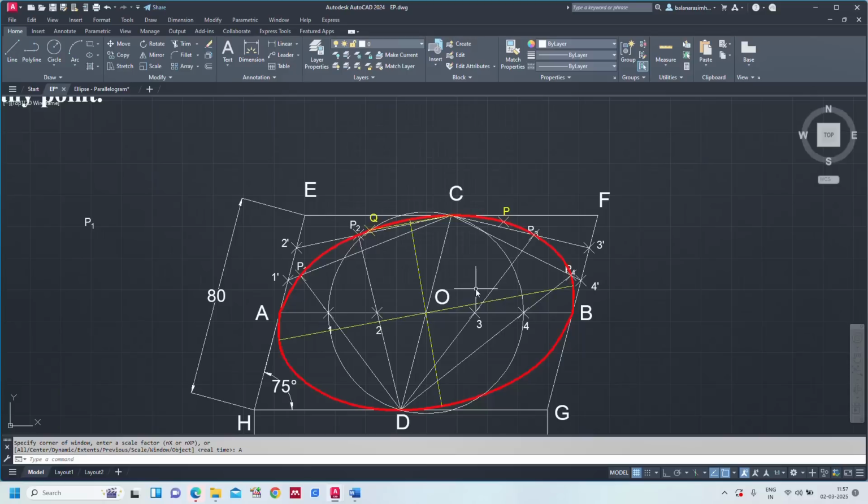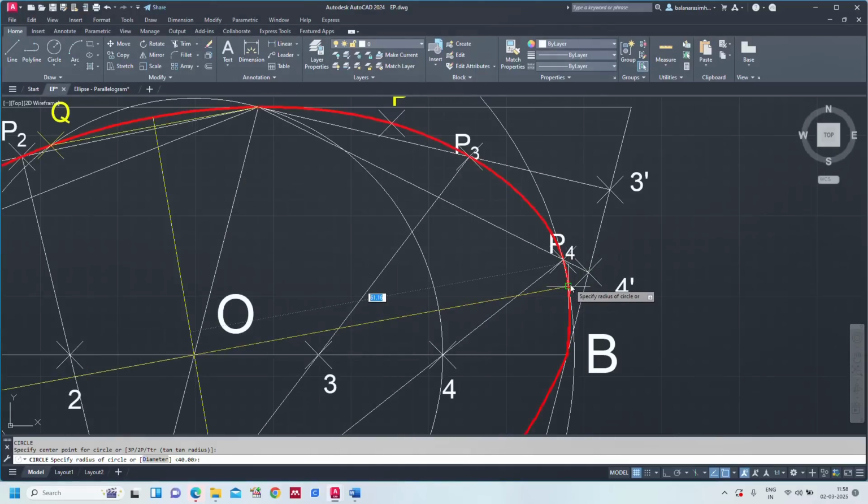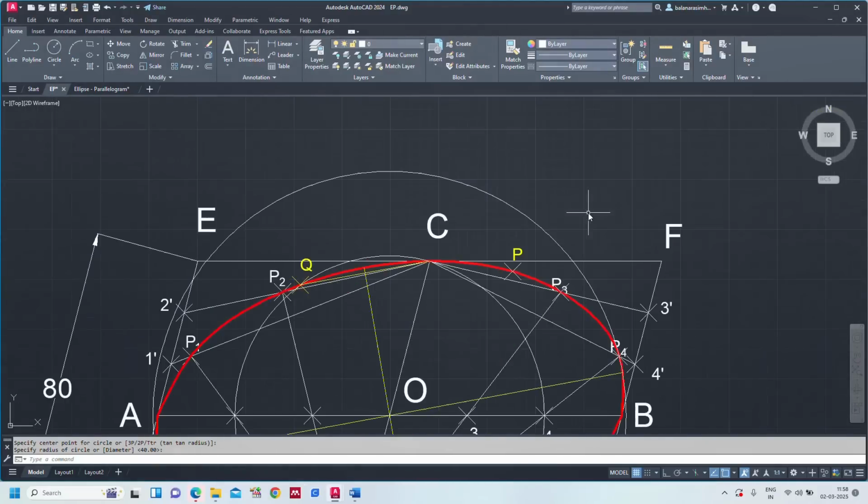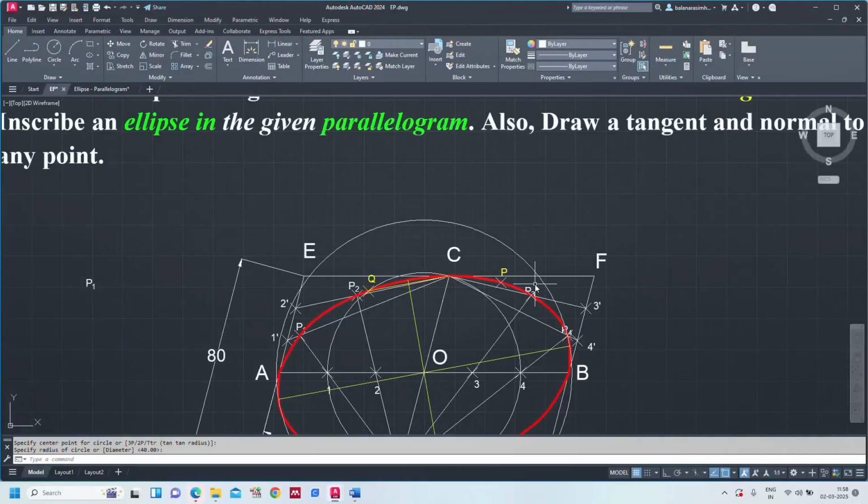So now I am going to draw a circle with this center and the major axis as diameter. Major axis, not the previous conjugate, the freshly and newly found major axis. Yes, see, perfect. This is the circle and this is the point. And from this point, I need to draw a line parallel to the minor axis.